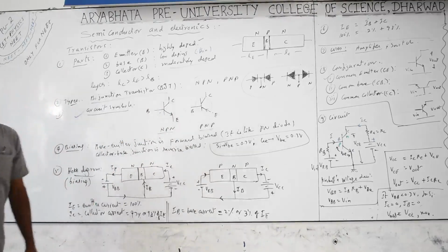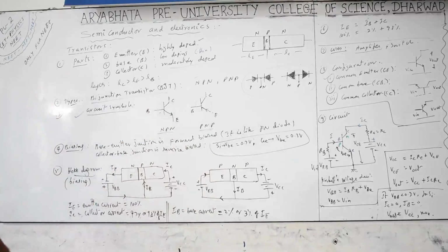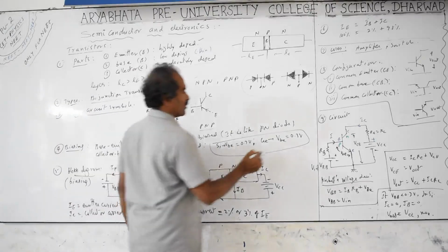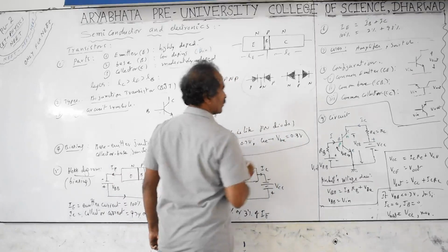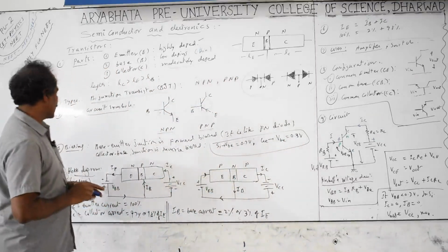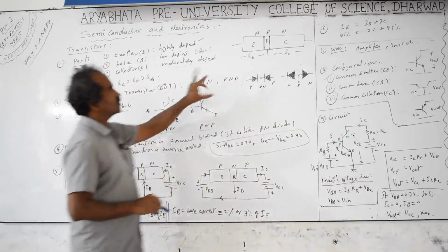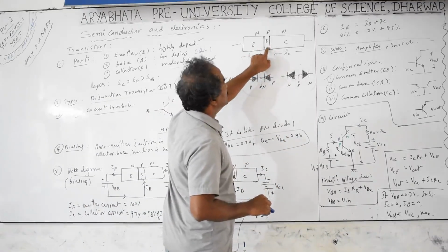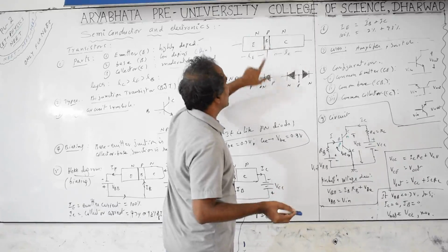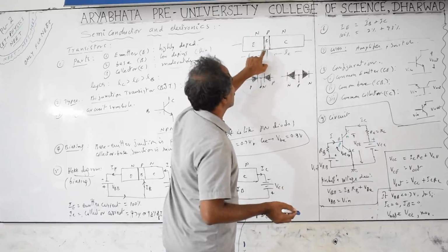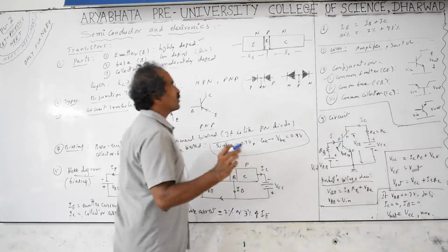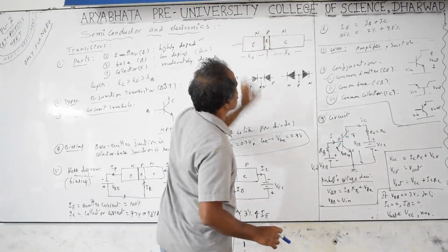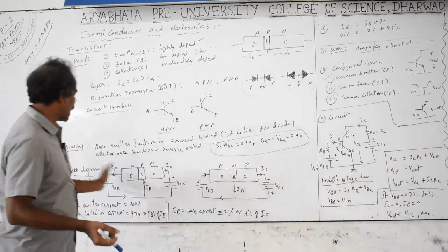Next, biasing. Biasing means what? Giving unequal voltages or showing partiality is the literal meaning, is nothing but called as a biasing. For the diode we have the forward bias and reverse bias. Here for the transistor we have two junctions, between emitter base and collector base. Emitter base junction acts like a diode, ordinary diode only. The gap between these two, the voltage between this emitter and base, that is a barrier potential because of the ionic regions. Ions are present here also, but this emitter base behaves just like the forward bias diode after biasing.